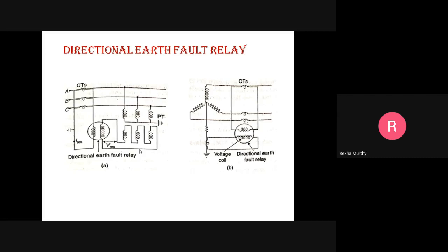Now let's move on to a new concept, distance protection. Distance protection is widely used. Where do we use this? It is widely used as a protective scheme for high and extra high voltage transmission as well as sub-transmission lines. This scheme makes use of a number of distance relays, which measure the impedance, or some component of the line impedance, at the relay location.